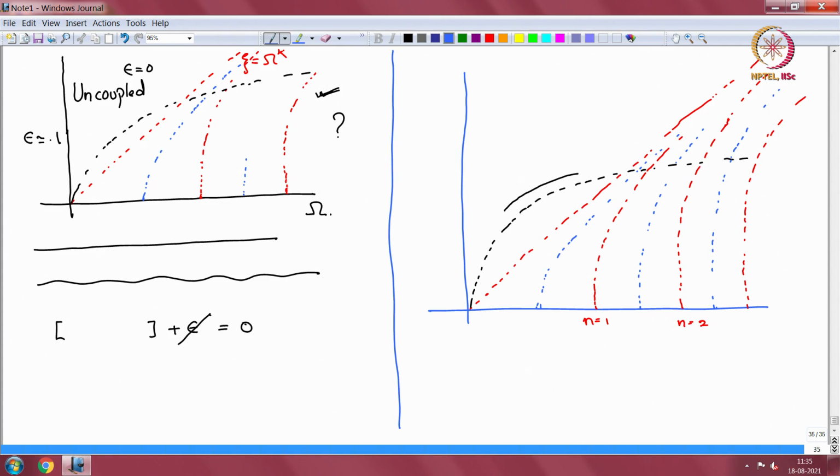So now this flexural wave, how does it change? Okay. So the acoustic plane wave will change, get modified. So let me use black. Get modified to this, and then as we approach the flexural wave, okay, it becomes the flexural wave and it crosses at this blue line intersection and it follows the next rigid duct cut-on.